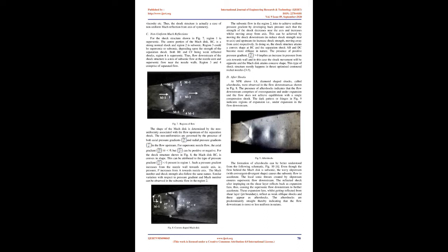The supersonic viscous flow inside the contoured nozzle, whilst operating under overexpanded conditions, developed a strong oblique shock called the incident shock, B, towards attaining equilibrium with the ambient conditions. Since the slope of the incident shock increased towards the axis of symmetry, thereby increasing its strength, the only possible reflection was Mach reflection. Thus, the incident shock was observed to reflect as a Mach reflection, with C as the reflected shock and T being the triple point where both the incident and reflected shocks merged.